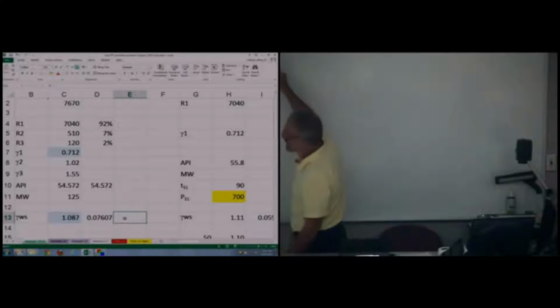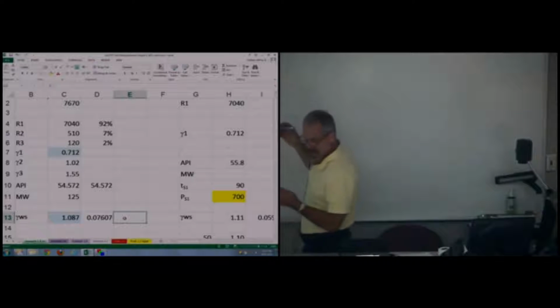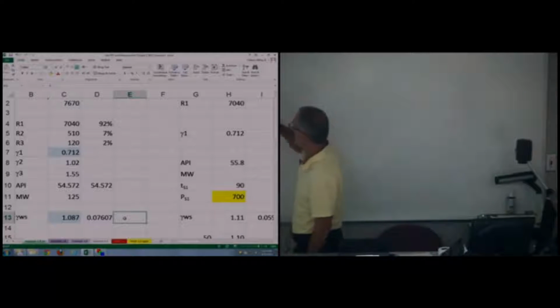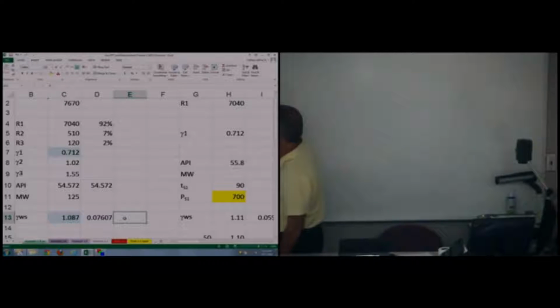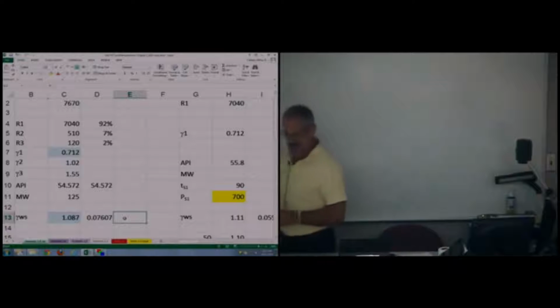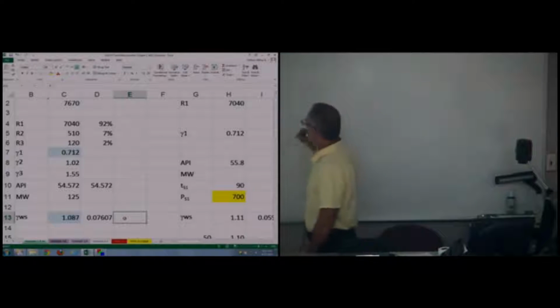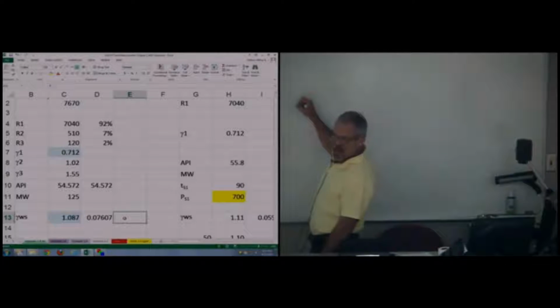A lot of times you'll see a gas gradient in an oil well, then it'll hit liquid level. That liquid level is real easy to find, lowering a pressure bomb in a hole, raising it, getting it back out, and getting pressure versus depth. And we usually plot this the way it physically looks. So here's our depth at 0, and here's our depth. I think in this problem we got 8,000 feet. If it's linear, it makes the problem easy.